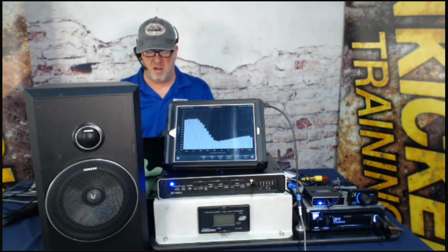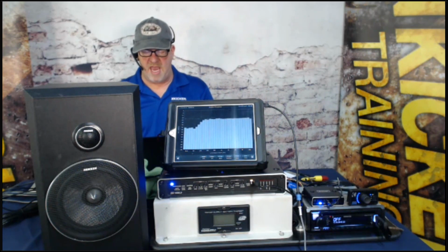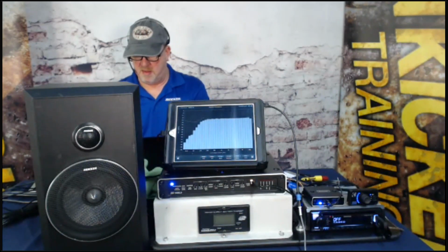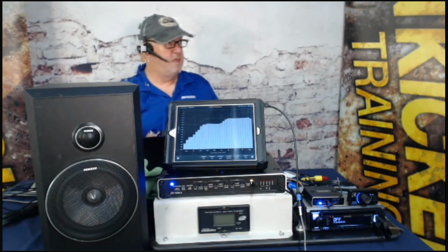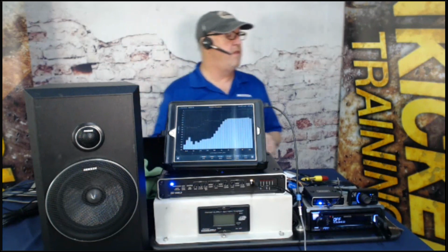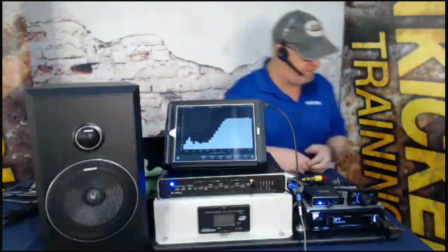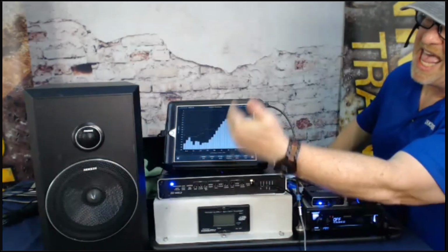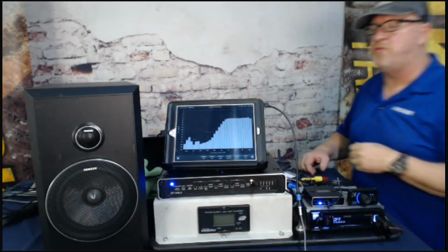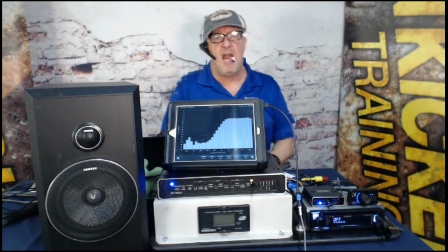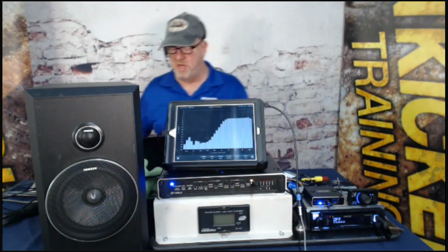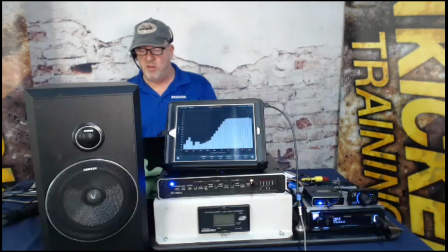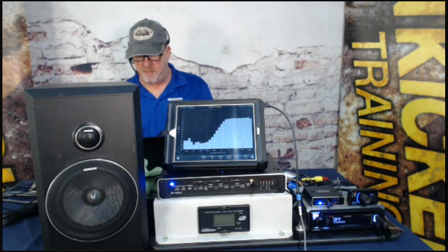So playing with the crossovers, once again, let's go back to this high pass crossover, turn it on. What if I had this signal? So now I think we lost our display here. So if we look at this signal, I've got a high pass frequency at a high pass point, more like a mid-range or a tweeter crossover. That is not going to be an acceptable signal. So once again, we can change the way the system looks by changing the crossover, and we know exactly what wires we need to tap into.